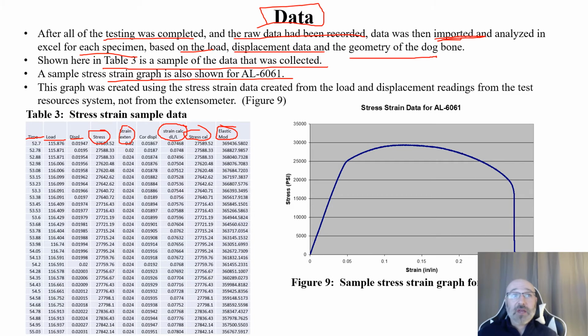If we're saying, okay, this is our stress, our strains, our elastic modulus for these specimens, well, is that accurate? I know we've done our calibration, we've recalibrated everything, all the test equipment, but is it correct? We know what our elastic modulus should be for our steel, or for our aluminum 6061, so we can double check it off of that and compare that to what we see for our results for our other specimens as well. So that's a great double check. And again, that's why we did all 4 of these, so we'd have multiple ones that we could run with each one of these specimens.